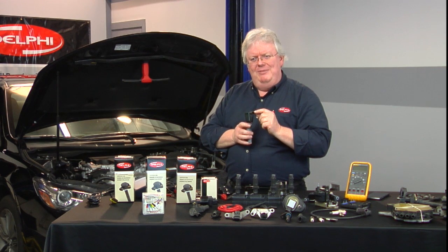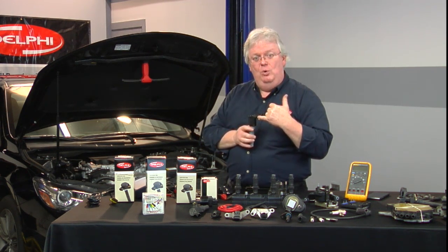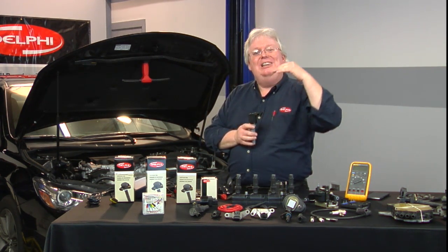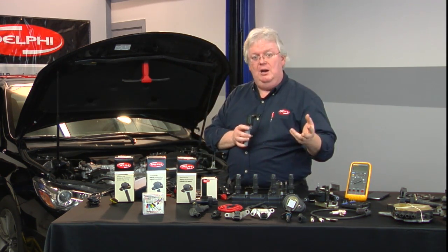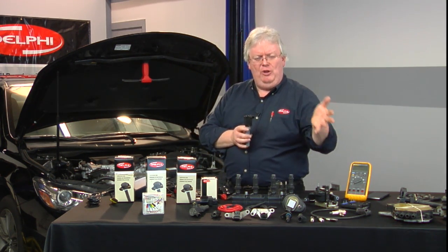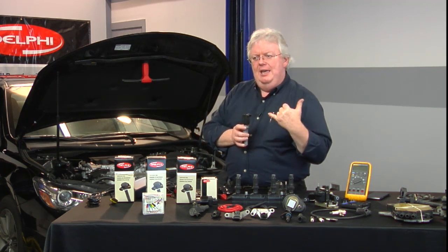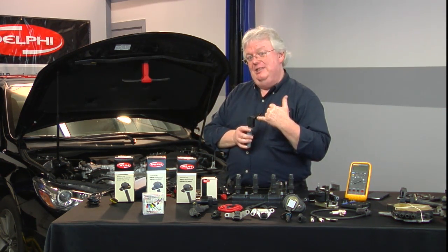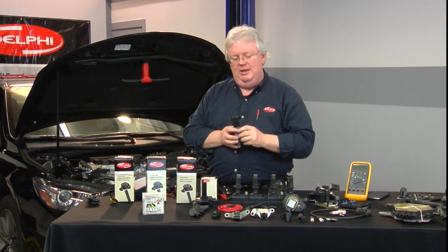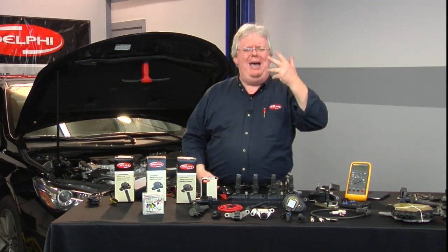That same wire, I back probed it at the coil just to see what the voltage level was. Never mind the current ramping, just what the voltage level was. So that was the blue trace. The red trace, channel 2 on the Pico, was the on-off ground applied by the coil driver circuit in the PCM. And that was giving me my primary pattern, I'm sorry, not secondary.